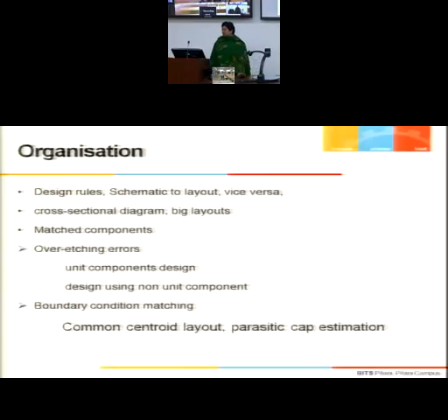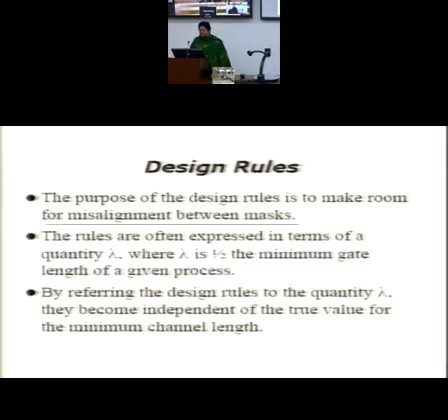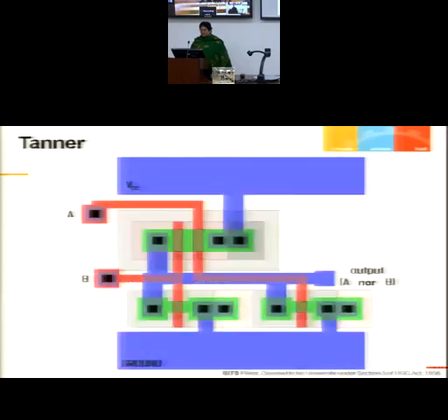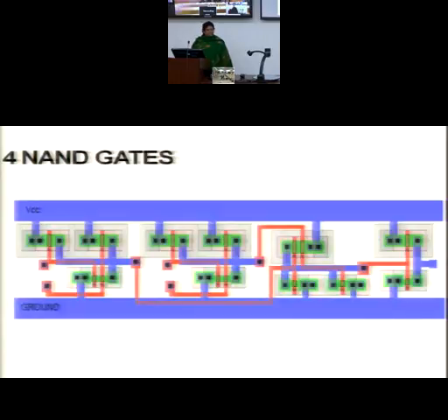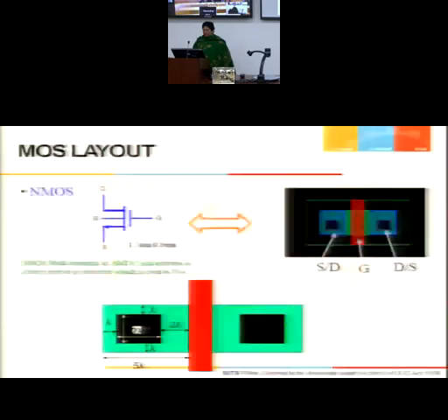Okay, so how do we go about that? Let us understand. If I have to make a certain layout, these are the layouts that we usually make. Do you have any practice of drawing layouts? You have. Okay, so these are all layouts. Now suppose you have to make a layout, as I am showing over here, a MOS transistor. This is going to be the polysilicon, that is the gate. It is a top view, so you have to keep visualizing the cross-sectional diagram also, side by side.